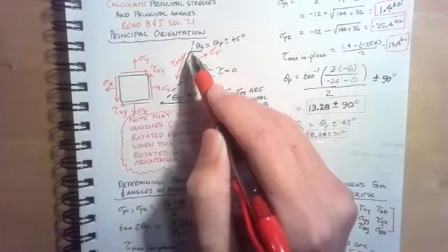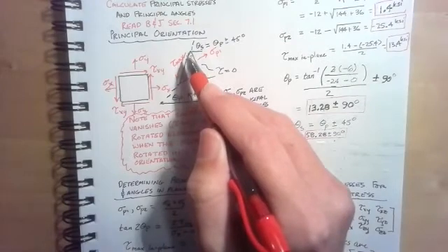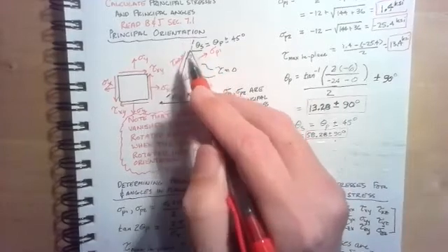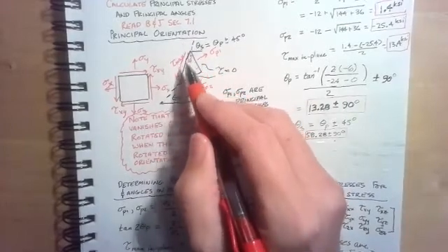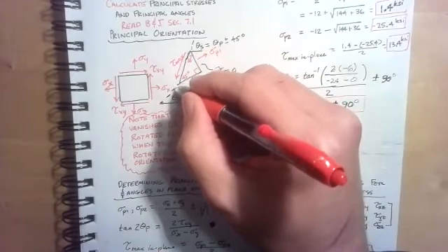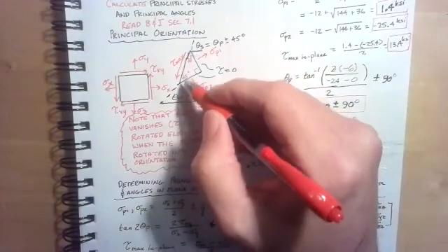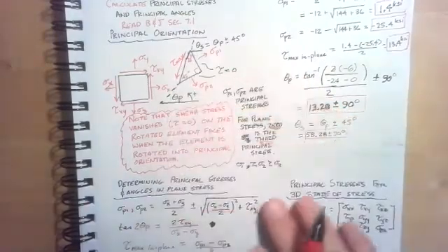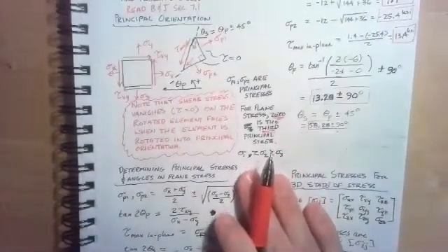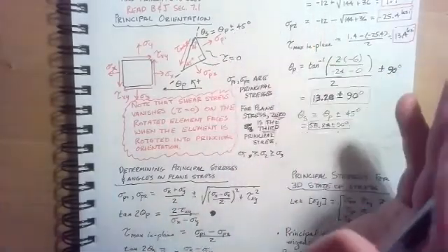Now, in a lot of materials, this is a very significant plane because most tensile failure actually happens because of dislocations sliding through materials, and it takes shear stresses to make that happen. So when shear stresses reach a critical level, you'll usually have failure along this kind of a band, and you'll usually see that. So we often want to know the orientation of where we would have the maximum shear, and if I wanted to do that, I would be aware that the shear angle is equal to the principal angle plus or minus 45 degrees.